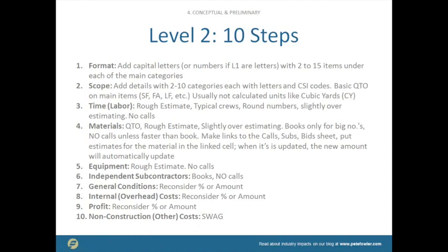Probably better to have between 5 and 25. A work breakdown structure typically is going to have at most 9 or 10 level 1 items. But in a construction cost estimate, because you're dealing with professionals who deal with estimates over and over again, you might have as many as 50 line items in the summary. And then for each level below that, you're going to have between 2 and 15 items at level 2 on the details page.